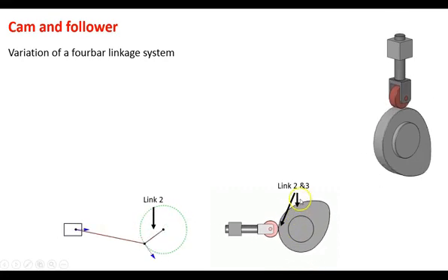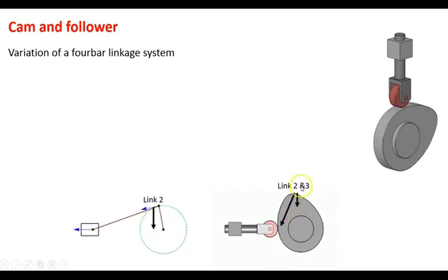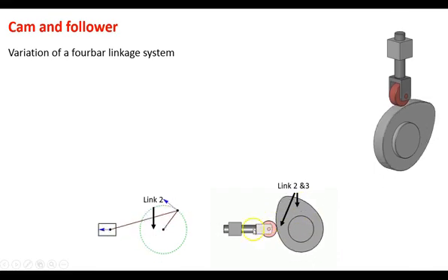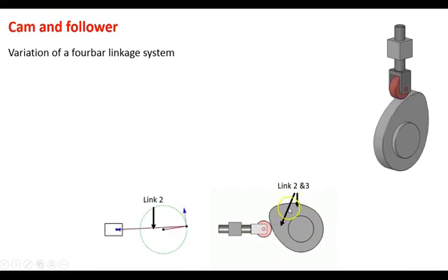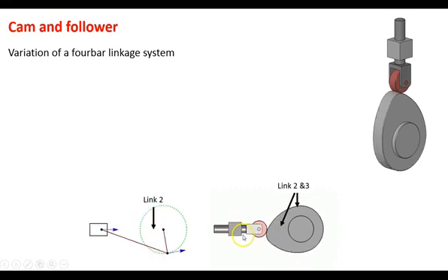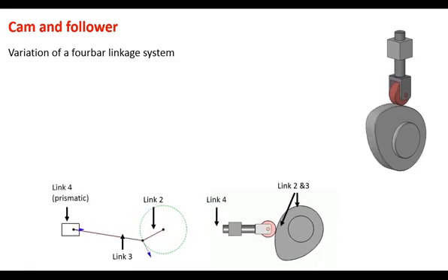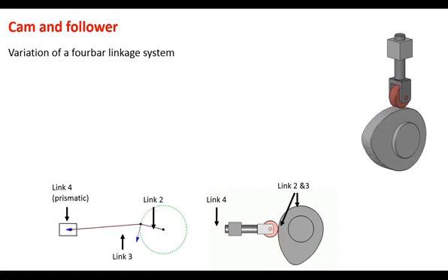So in this case, your linkage 1 is still implied. Linkage 2 is the base, the round part of the cam, the bottom of the cam. Linkage 3 is actually helping with the extending or the horizontal motion, which would be the purpose of that lobe. And the prismatic linkage would be here down at the end, which helps create the linear motion. So if we were to try and draw a really good analogy, you can see there is a relationship.